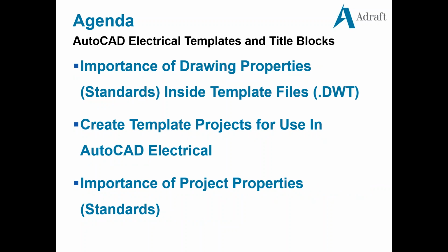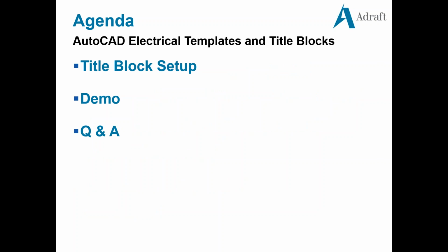We're going to talk about why it's so important to use template files inside of AutoCAD Electrical, because it drives your standards, it drives your company standards, your customer standards. So we're actually going to create one. We're going to include those standards in our drawing templates. We're also going to talk about the project properties that would be associated to a project template. Again, you're going to build your standards into the projects to match what you have in the drawings.